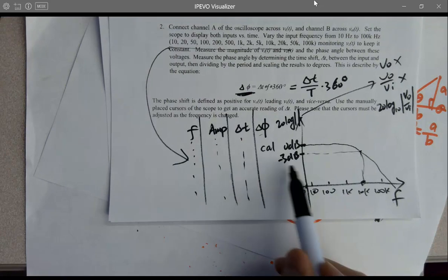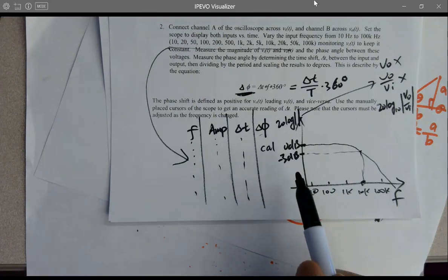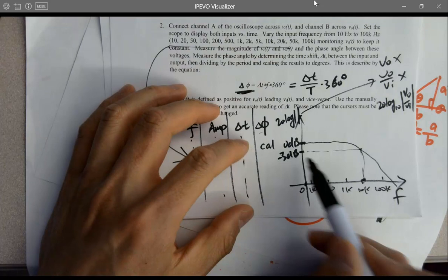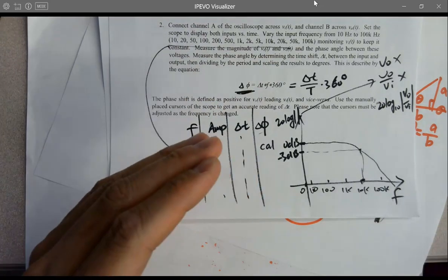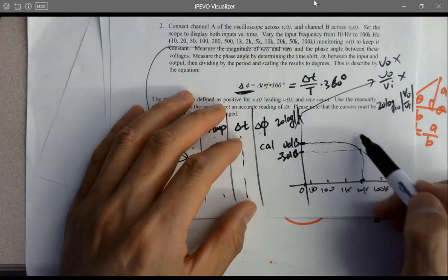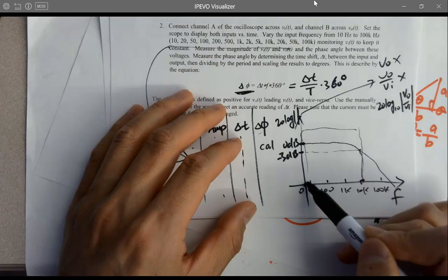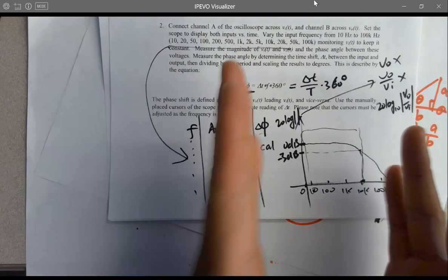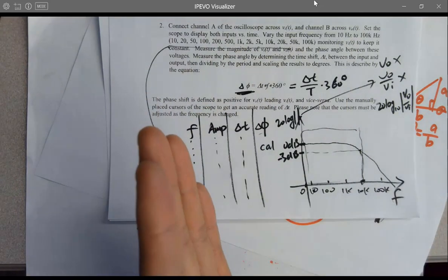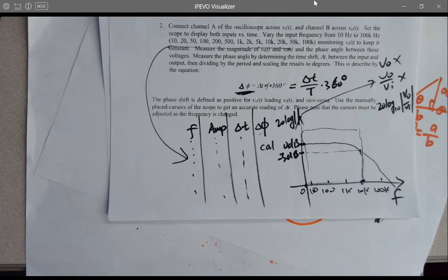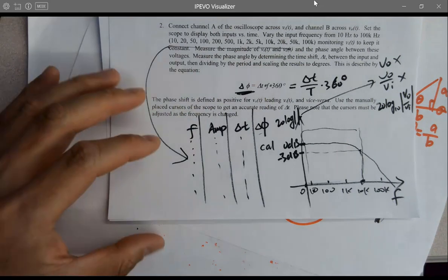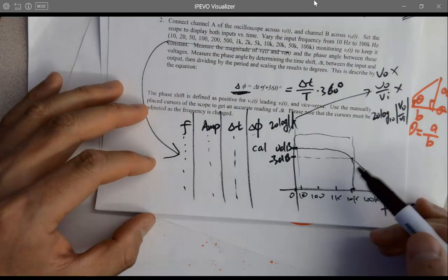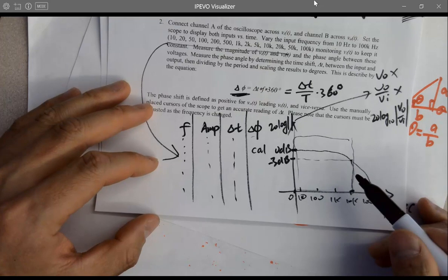So the reason we use that one is because we consider the minus 3 dB is still not a significant attenuation. We consider all the frequencies here is passing through the filter, not getting attenuated significantly. That's the boundary of signal being filtered, signal being maintained, not being filtered, but attenuated. All right.